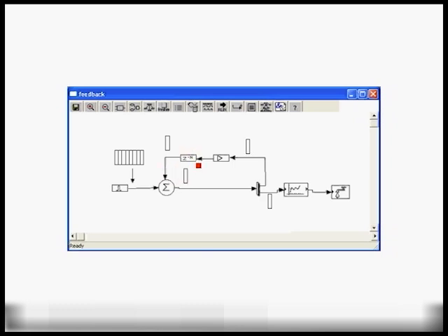Now, the delay block typically would take its input sample and delay it by one sample and output it, as shown over here. But during the initial run, beginning of the simulation, we actually don't have an output from the adder to the node block, to the gain, to the delay.